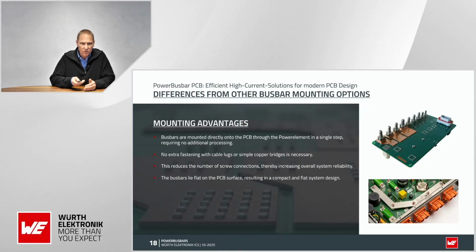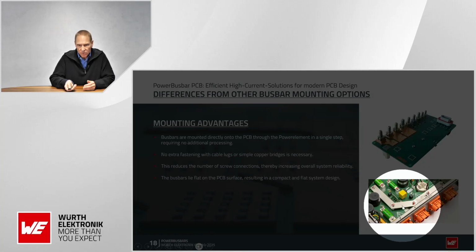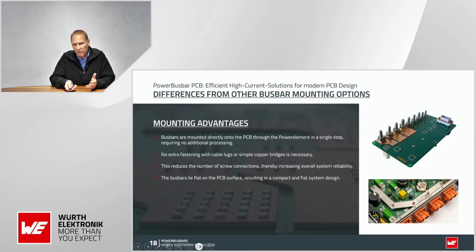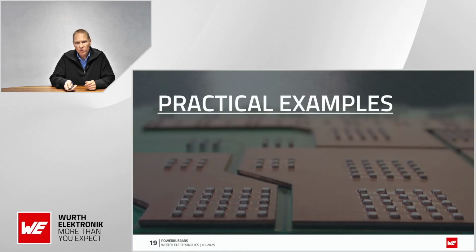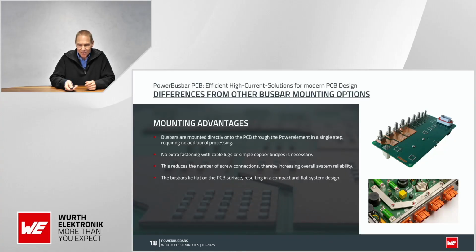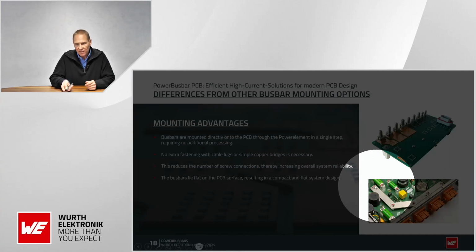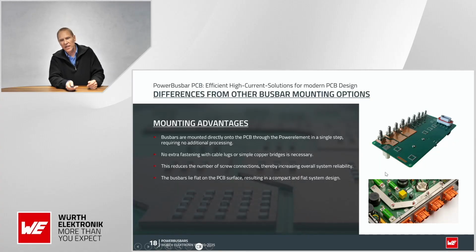There is also no need to go from one connection point to another with cable lugs or with copper bridges. And so you will also reduce the number of screwing connections in your application, and this will also increase the reliability of the overall system. And since the bus bars are lying flat on the PCB surface, this results in a compact design and also in a flat system design.